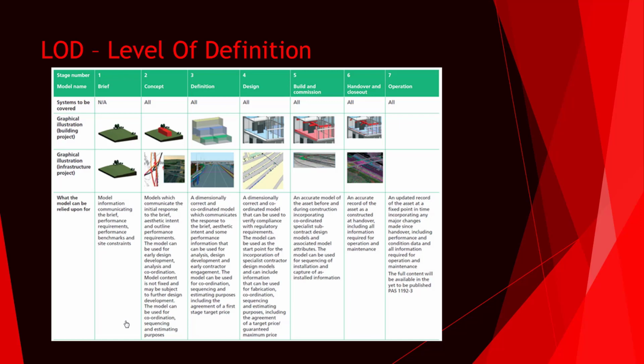One of the last things to touch on is the level of definition. When you're creating these families or components, the best thing to establish first is the level of definition that you're using. If someone's just asking for concept work, you're not going to produce an in-depth model or family for that. For instance, with your brief or concept, you're essentially starting with just a block on top of the topography, whereas as you move over into the build and commission side of things or design, you're going to have your in-detail family or component. You're going to have all your structural connections in place, and whatever other necessities are needed for that.